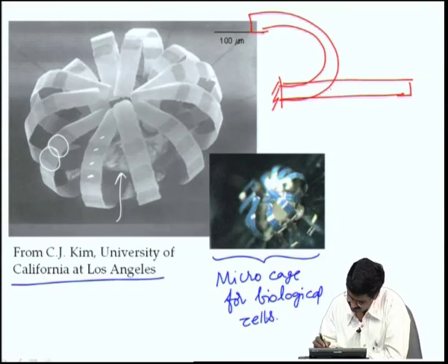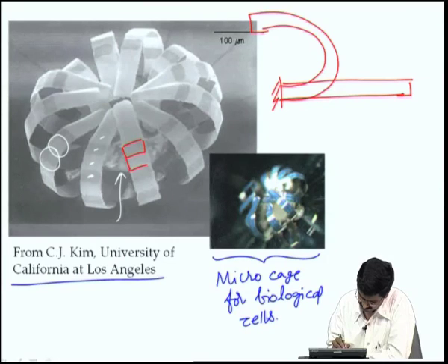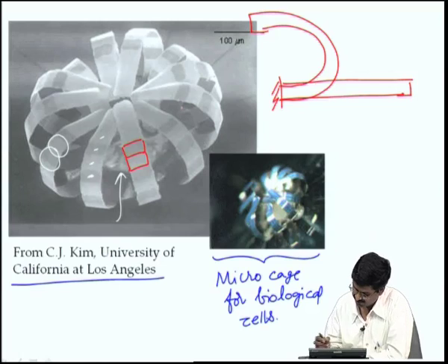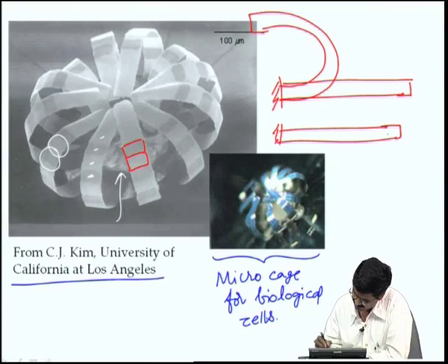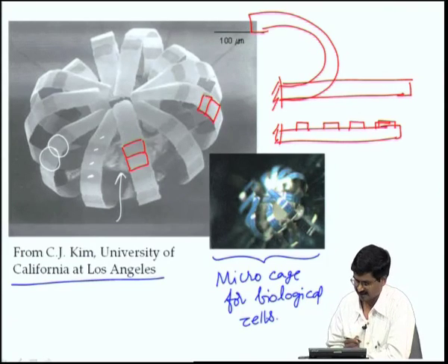Now, if you were to just leave it, it can actually go and become completely closed. If the residual stress is more, the bending will be more. But the reason for having these bright and dark portions is that they have taken a beam and put stiffeners in some places. Whatever has curled up which has this stiffener looks a little bit darker compared to the other one which is slightly brighter. So, they have added these ribs on top of the beam.